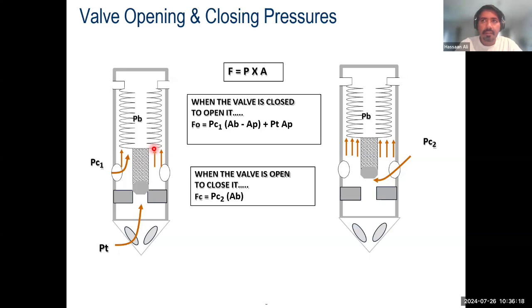The other thing is that normal air has a lot of moisture content, which we don't want downhole. One of the things that is very abundantly available in oil and gas fields is natural gas. So we try to use natural gas because it is available for the gas lift injection. So when we talk about the pressure over here, this is the pressure of the natural gas. So your methane. Methane is usually your most abundant, or when we talk about the injection gas, that is the primary component of the injection.